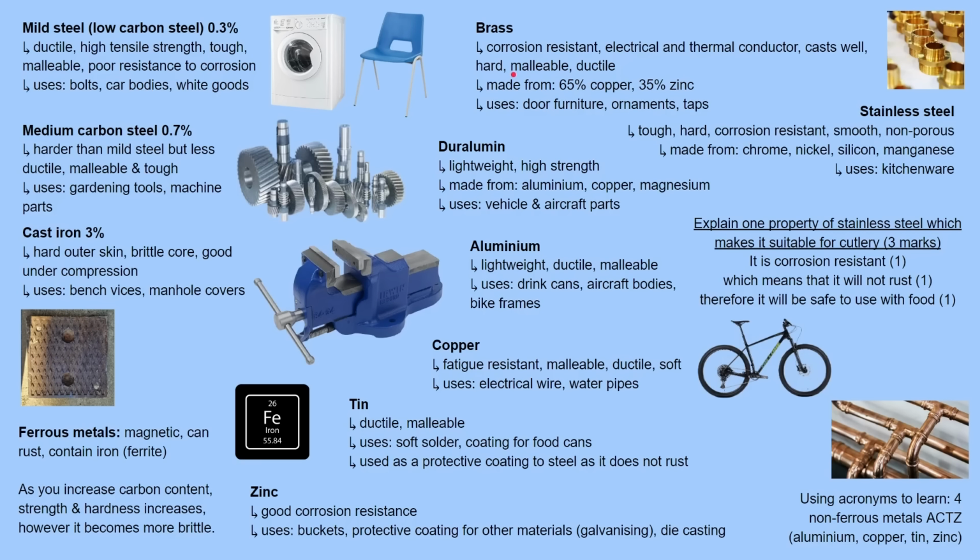Normally, as we've seen, if a metal is malleable, it's also ductile. Malleable means it can be hammered or shaped without fracturing. And ductile means it can be pulled or stretched almost like a string, or like a pipe. Copper pipes are ductile because copper is a ductile material. It can basically be pulled into a wire. So here we have washers or bolts or something that are made from brass.